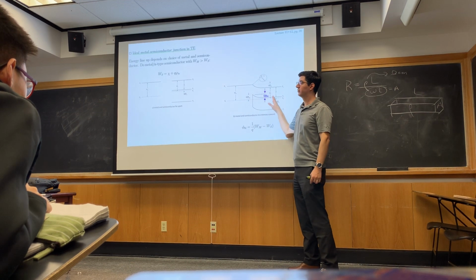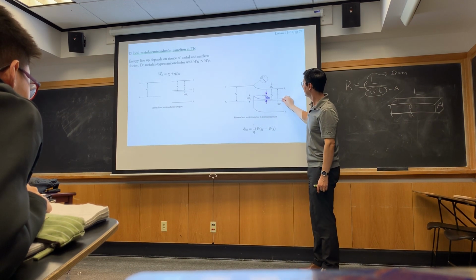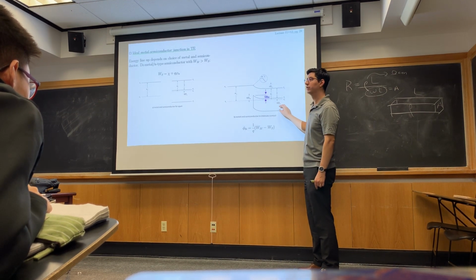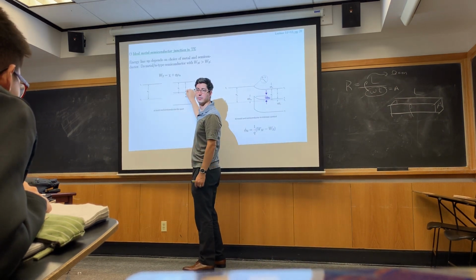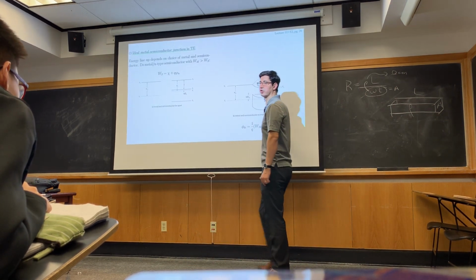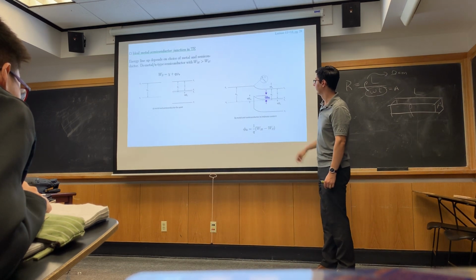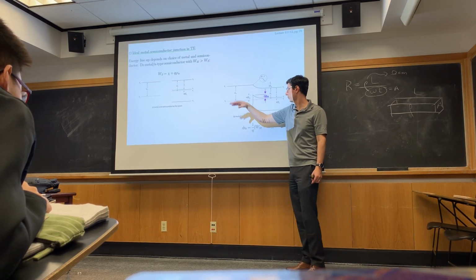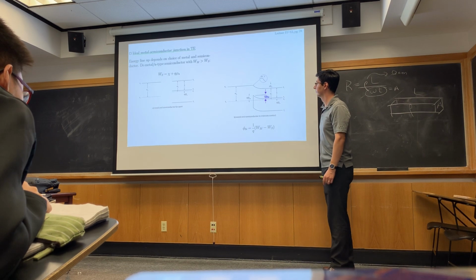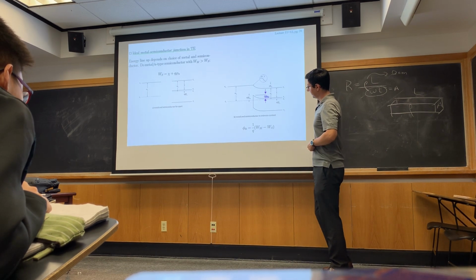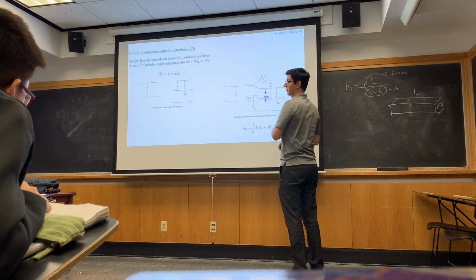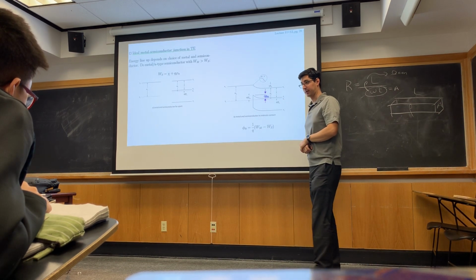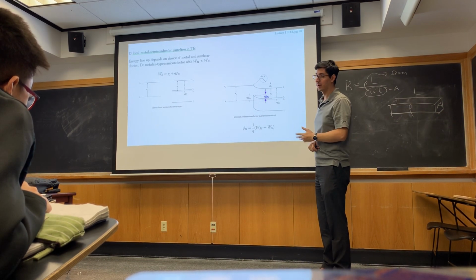And far away from the junction, EC minus EF, which we're calling q phi n, is the same as it was earlier, right? Far away from the junction, nothing should change. Sure enough, if you ignore this part, everything's the same far from the junction. But right here, I have a discontinuity. Well, we know we have a discontinuity.